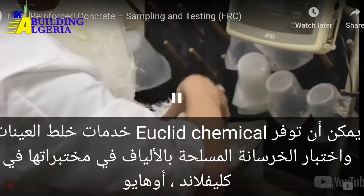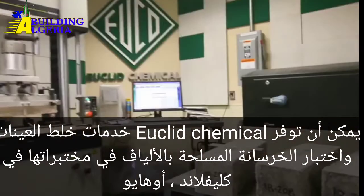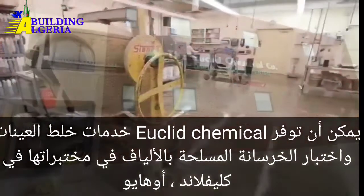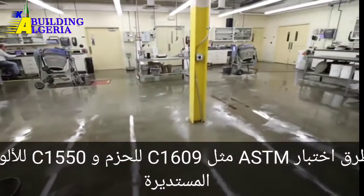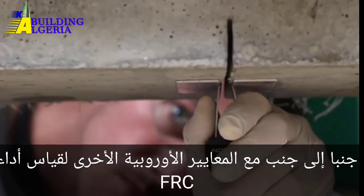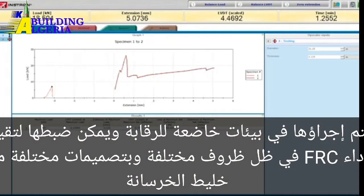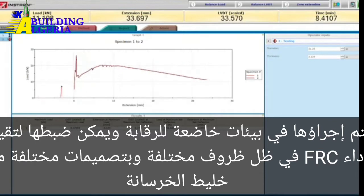Liquid Chemical can provide mixing, sampling, and testing services for fiber-reinforced concrete at their testing laboratories in Cleveland, Ohio. ASTM test methods such as C1609 for beams and C1550 for round panels, along with other European standards for measuring the performance of FRC, are conducted under controlled environments and can be set to evaluate the performance of FRC under different conditions and with varying concrete mixture designs.